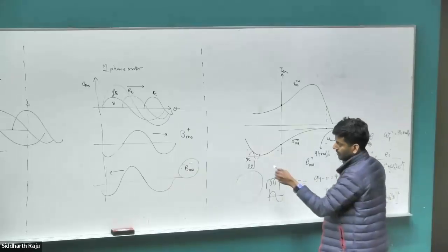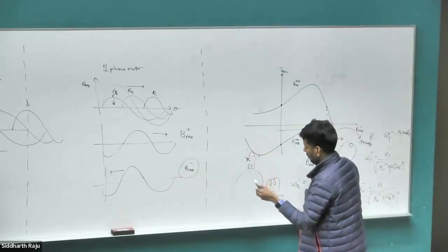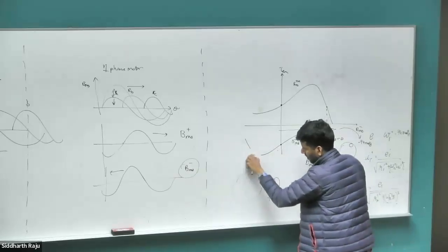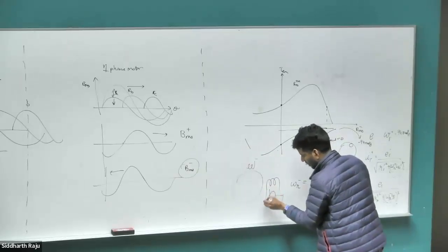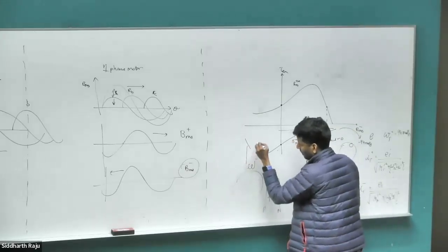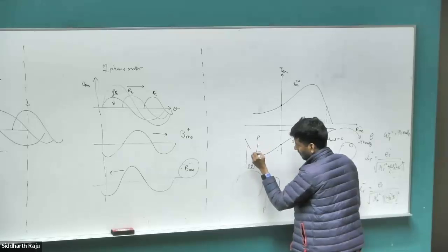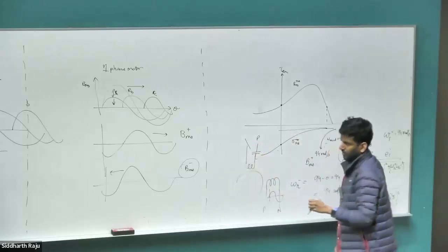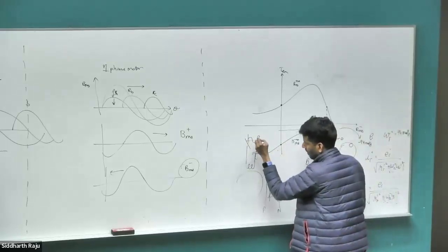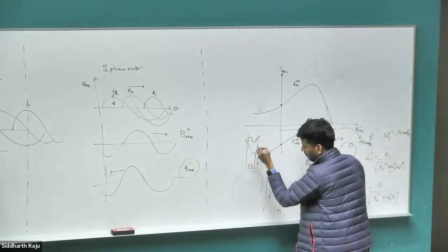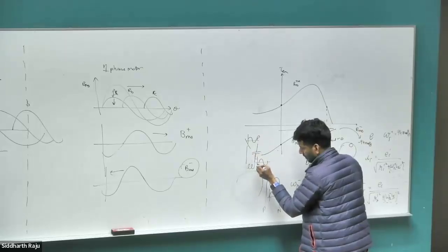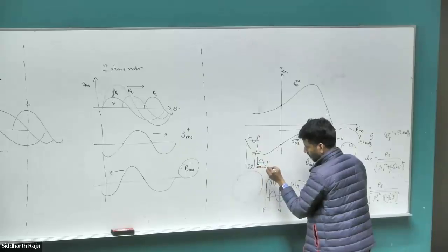So what they do is, we don't have a two-phase power supply; it is always typically three-phase or one-phase. So how do we get this two-phase power supply? They basically use the same one-phase power supply that we are getting here. So P and N, same P and N here, but instead they put a capacitor in series. What that effectively does is, whatever the voltage here is, it phase shifts it, not precisely by pi by 2, but very close to pi by 2.